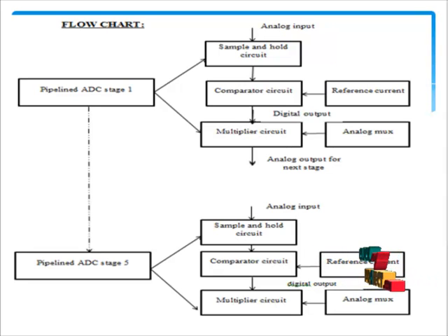We have defined the stages step by step as a low-cost foreground calibration. The calibration is performed in the comparator sections, and we get the reference voltage from there. The reference current and voltage are dedicated to calibration, with capacitor size limited by matching, noise and power consumption. Additionally, the proposed partial non-overlapping scheme increases the settling bandwidth requirement in the amplifiers, and we also improve the power. Then we go to the multiplying process.